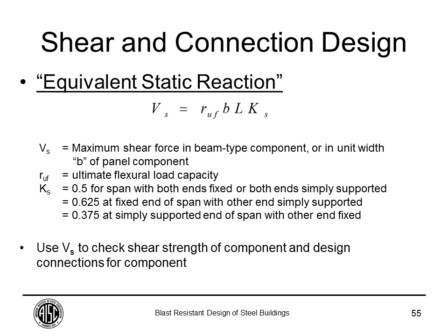This is when we use the equivalent static load approach. VS is the maximum shear force that a beam can transfer based on its flexural capacity, and the way you calculate it is you take the ultimate resistance, which is the RU of the member.